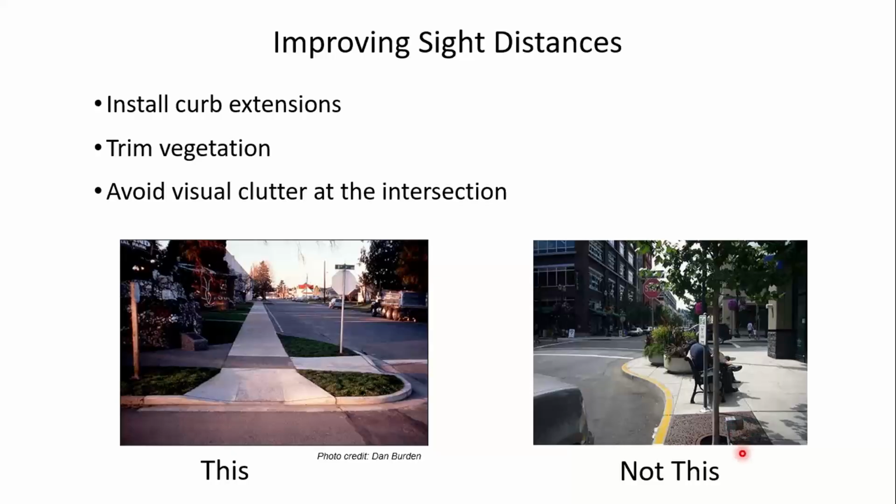There could be someone in a wheelchair or a child or some small stature pedestrian walking toward that crosswalk or even waiting on the corner, and that vegetation may prevent drivers from seeing that pedestrian. So keep that in mind. I don't mean to discourage these aesthetic treatments, but I think they need to be appropriate and shouldn't interfere or block sight lines.